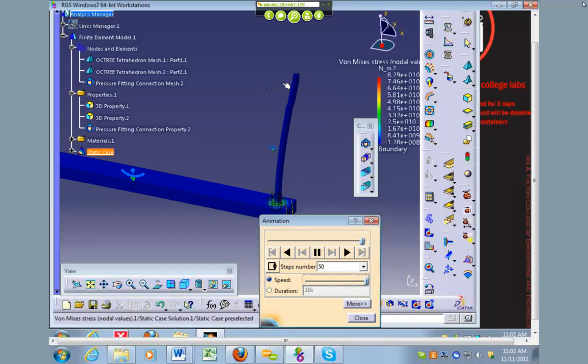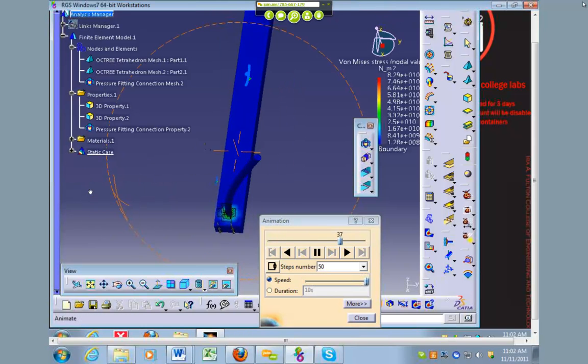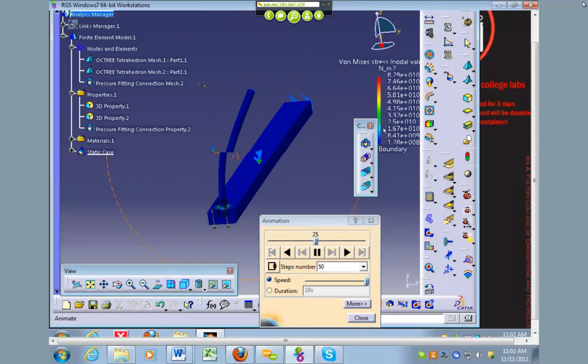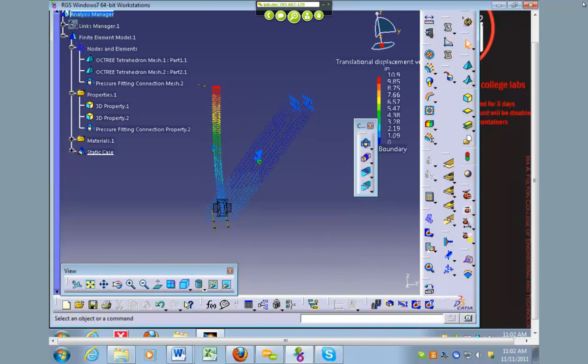What view is that right now? That's the von Mises, you said? Yeah, this is the von Mises stresses. I'm just curious, because I can show you my different... You did a clamp at the end of the bar, correct? Yeah, I clamped it. So they're getting stresses up close to back by the clamps instead of just right there, right? Yeah. So they're getting lots more.